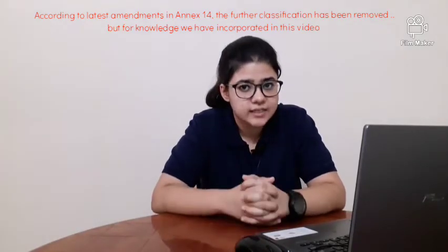In case of category 3A, the decision height is lower than 30 meters or nil and RVR is not less than 175 meters. In case of category 3B, the decision height is lower than 15 meters or nil and the RVR is less than 175 meters but not less than 50 meters. And in case of category 3C, the RVR is 0 or nil and the decision height is also nil.